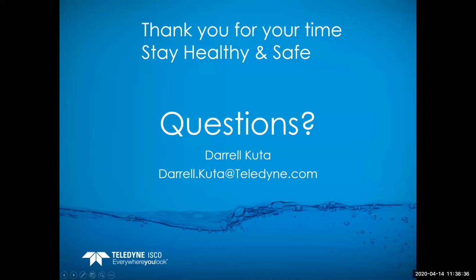Another question, Darrell, is what is the typical depth of the laser beam? The typical depth of the laser depends on the actual water depth, and it reads at a percentage below the surface of the water. So it will read at 5% below the surface, at 8%, and 11% below the surface of the water. If I only have 1 inch of water that we're reading at 5, 8, and 11%, it's going to be very close together. If I have 5 feet of water depth, then they're going to be spaced out a little bit more.